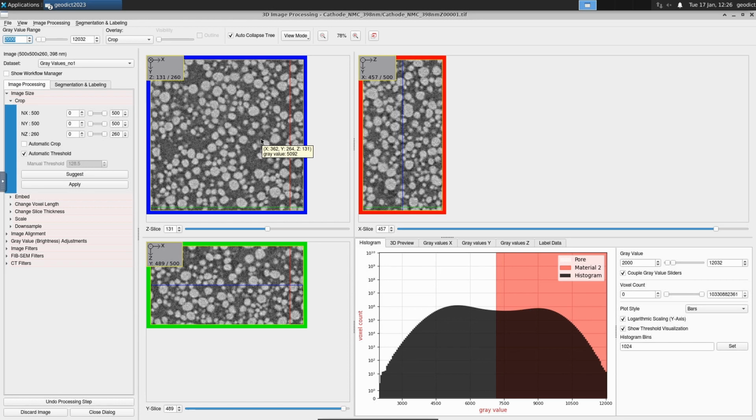But before we do the filtering, we want to go into the first break. Before this, I will show you how to save the volume field. If you got lost during the process here, we can all start by loading the volume field anew and doing the filtering. For saving, go up here to File, and then you could either choose to save it as a 2D image stack or save a 3D image. A 2D image stack will create a lot of files and is usually larger and takes longer to load, so therefore we choose to save directly a 3D image.